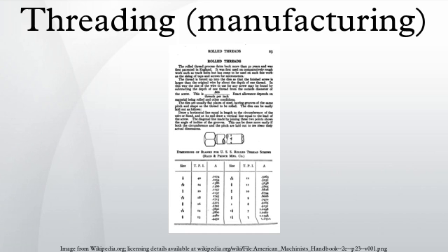Materials are limited to ductile materials because the threads are cold-formed. However, this increases the thread's yield strength, surface finish, hardness, and wear resistance. Also, materials with good deformation characteristics are necessary for rolling. These materials include softer metals and exclude brittle materials, such as cast iron. Tolerances are typically ±0.001 in, but tolerances as tight as ±0.0006 in are achievable. Surface finishes range from 6 to 32 microinches.